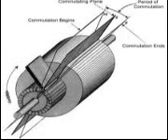Mounted on a shaft, it rotates through the magnetic field produced by the field coils. The core of the armature acts as an iron conductor in the magnetic field and, for this reason, is laminated to prevent the circulation of eddy currents. There are two general kinds of armatures, the ring and the drum.